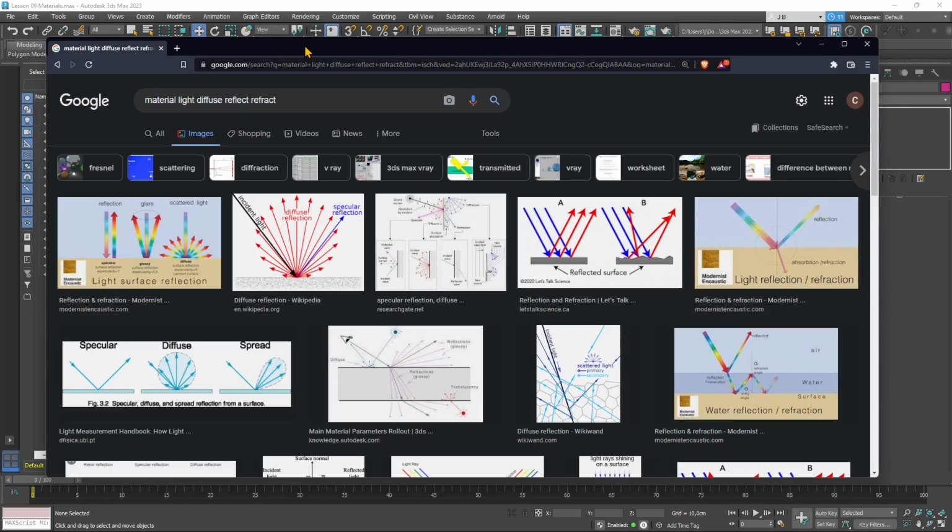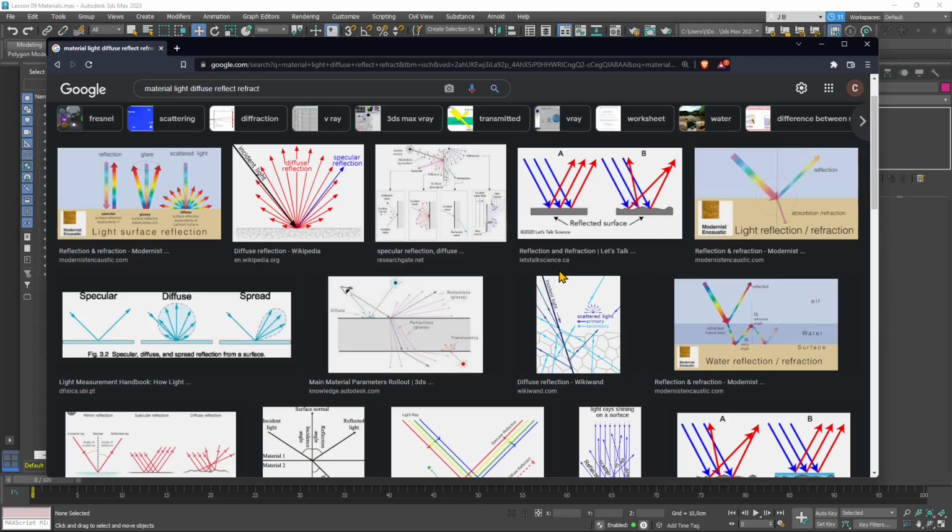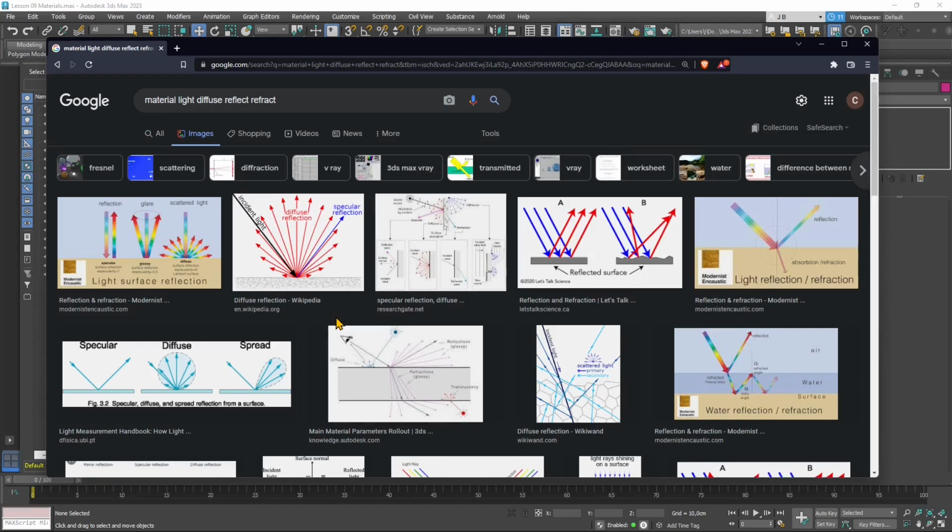So we said that material look is just how a surface reacts to lighting. So this is where it's all happening here. So if the light bounces on the surface, you're gonna have two types of bounce. So diffuse means it's not gonna have a reflection and not have specularity. When you have a concentrated reflection, you're gonna have specularity. You're gonna have like mirror reflection. So the light can be scattered on the surface or get back to your eye in a concentrated beam, and this is gonna make the main difference between a diffuse or rough material and a specular or glossy material, basically.